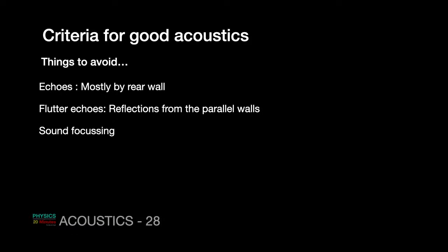Sound focusing: when you are putting so many sound reflectors at various places, it may happen by chance that at some point sound gets focused strongly, and at some point sound may not get focused that strongly, and that creates an imbalance that needs to be taken care of. Unless it is intended, sound focusing needs to be avoided. Intended means, as I told you, if you go to Bijapur, Gol Gumbad is a monument. Stand in the gallery, whisper at one end, and you will hear clearly at the other end. That's a whispering gallery. There the sound focusing takes place.